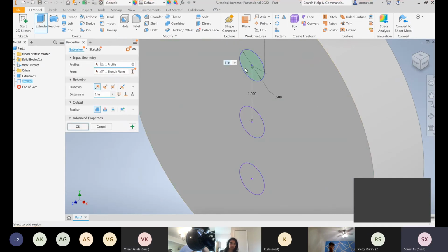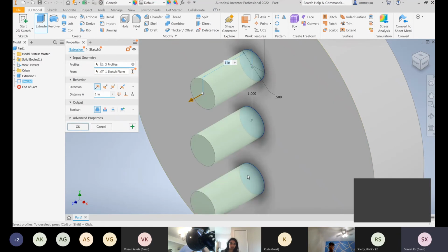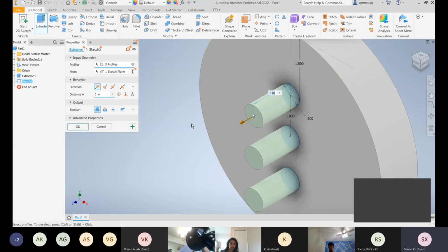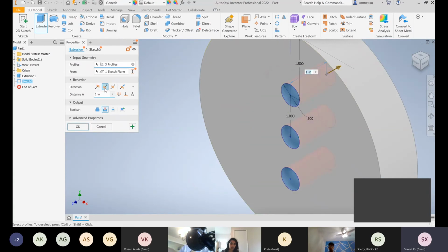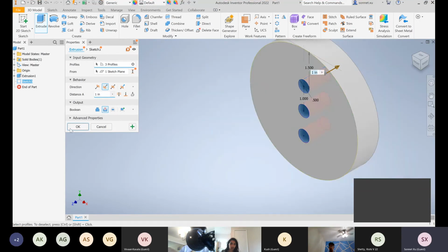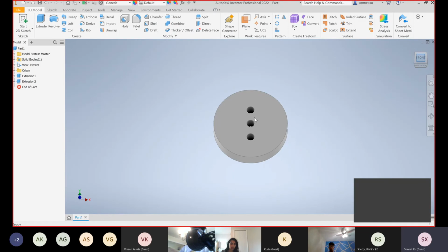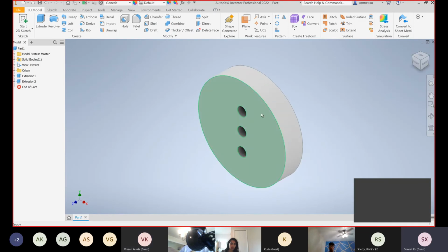So just like we did right there, you do the extrude, right? But obviously that's not really what we want our buttons to look like. What we're actually going to do here is you can flip this. And if you flip direction, you'll notice from down here, it went from join to cut. So it's going to cut some holes in the shape that we just made. So do you guys see now how it sort of looks like a button a little bit? So is everyone here?